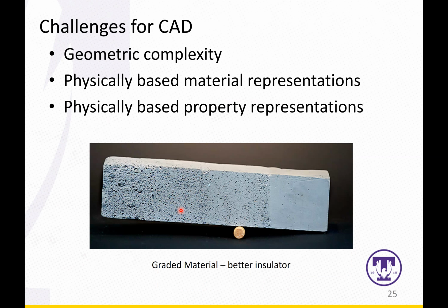And here also shows a graded material, right? Basically, this is just an illustration, not meaning this brick is additive manufactured, but you can see the concept of the graded material, right? So you could have softer material or stiffer material, and it can be manufactured in the same process, which is quite difficult to do using conventional ones.